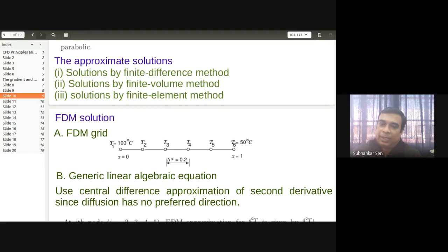Now in this step, the continuous domain is discretized into subdomains. So this is a subdomain. In finite difference, this intermediate zone is not important. It has no importance. Only this length is important. Only these are the nodes, these small circles. These are the nodal points. We shall discretize the governing equation and write it at the nodal points, and then we shall generate the system of equations and solve it. So let us show what we have done.